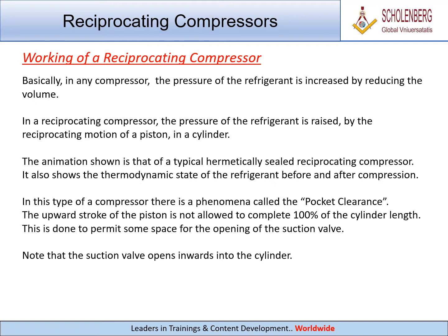In this type of a compressor there is a phenomenon called the pocket clearance. The upward stroke of the piston is not allowed to complete 100% of the cylinder length. This is done to permit some space for the opening of the suction valve. Note that the suction valve opens inwards into the cylinder.